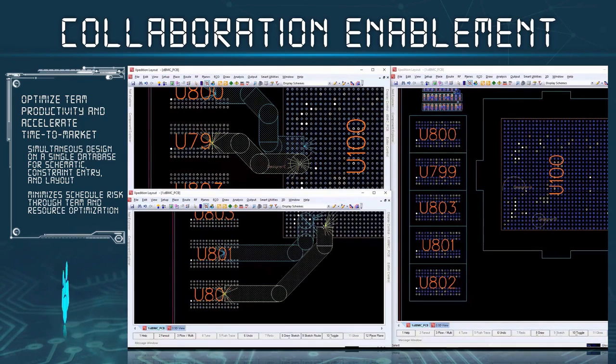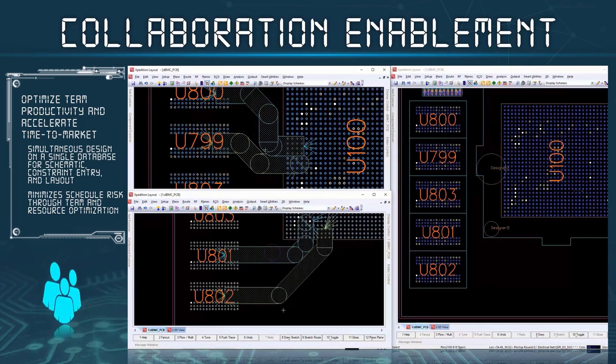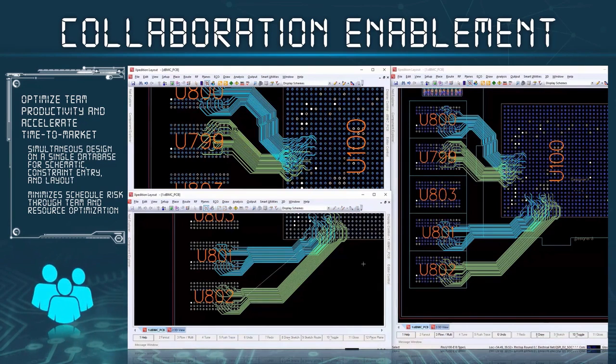Again, as the users on the left are working, their cone of influence is clearly visible to the user on the right. Next, the user on the right will use SketchRoute to quickly route the data nets. As before, when the nets are routed by the user on the left, they will immediately be displayed to the user on the right. Some of the nets were not completed during sketch routing. The sketch router's highest priority is quality. It will not add a connection if there's no room. As such, both designers will use HugRouter to push and shove routes to complete the open net.